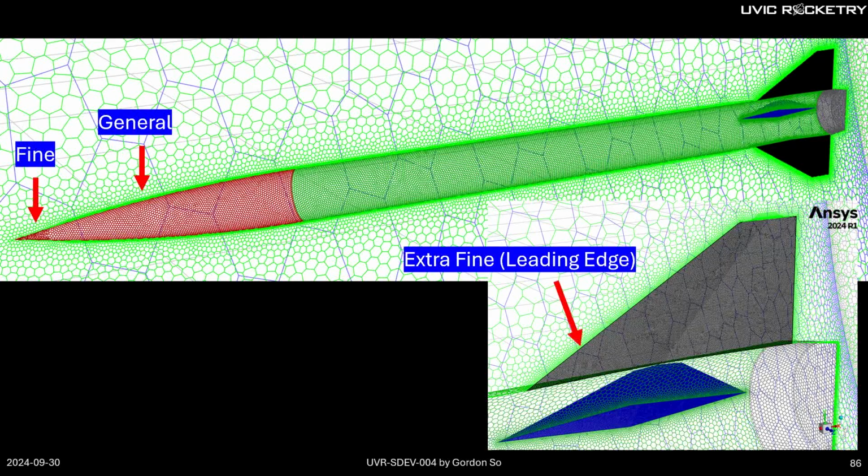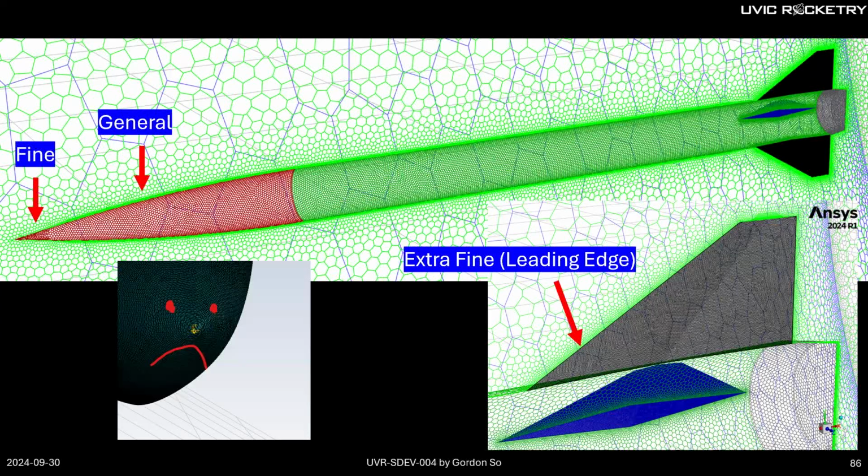And then on the leading edge, because again it's a sharp edge, and from what I find, I need a really fine edge. So I define really small elements. I think at one point I'm doing 0.5 millimeters or even smaller, which is pretty small for CFD. And from this, you will see a jagged mesh because you see, oh, I'm missing elements. It's not a smooth surface, but that's okay, because the big picture may not even matter. But spend the most effort to try to make your surface mesh look pretty decent, and proceed.